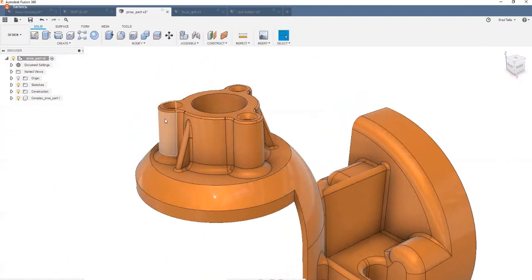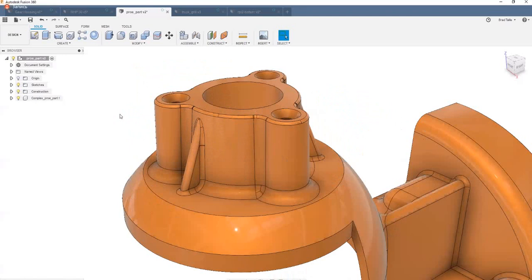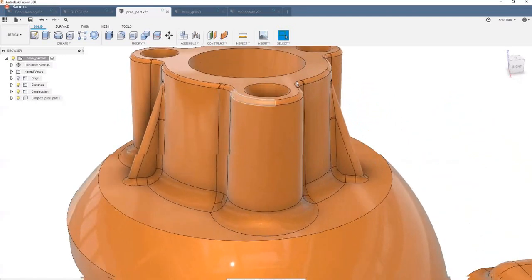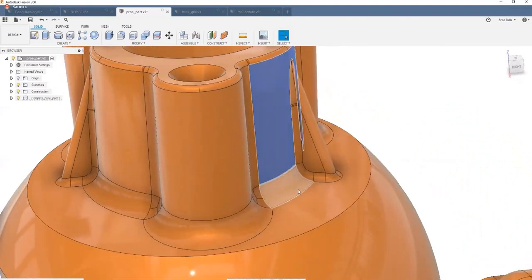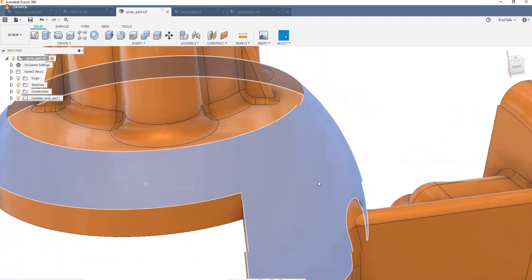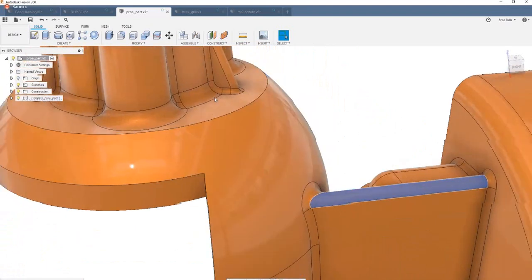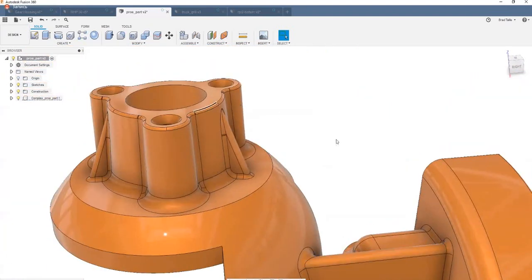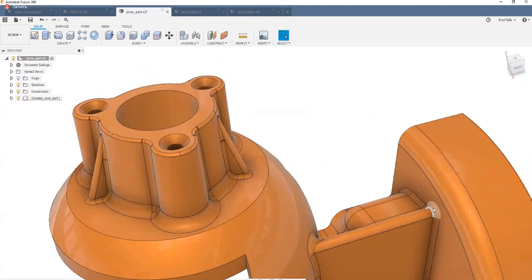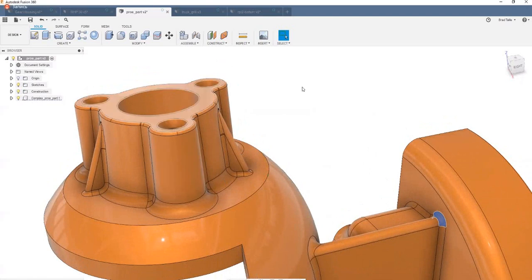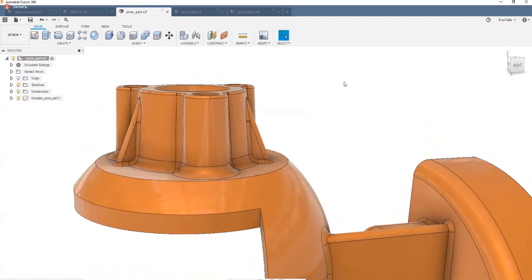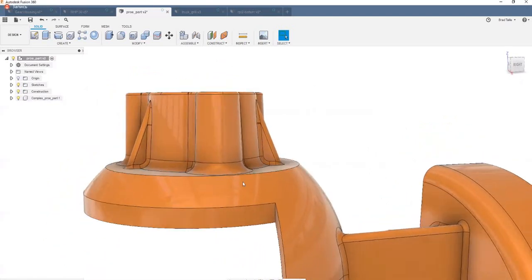Okay, so let's work on this one. Now, here's another tip. There's a lot of problematic fillets and stuff on here, and this fillet touches this face, which touches this, which touches this, etc., etc. So believe it or not, if I try and do something up here, but there's something mathematically wrong way over here, it might actually fail because it just can't solve that problem. But I want to be able to work on this area. So we're going to take the wound and heal method to the next level. We're basically going to amputate this whole section off.